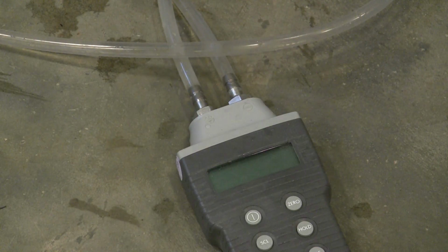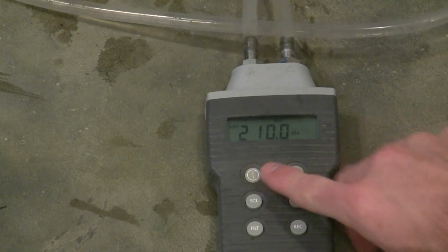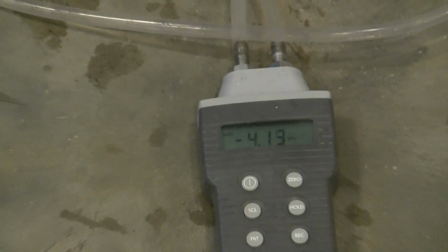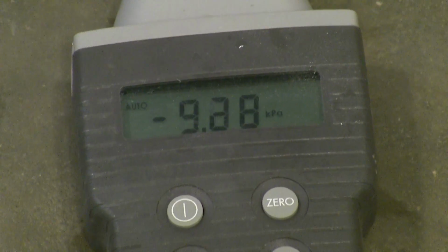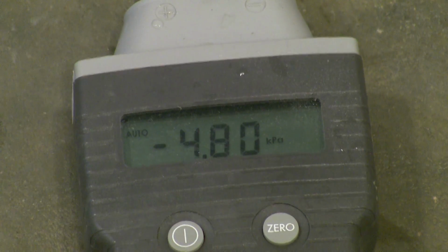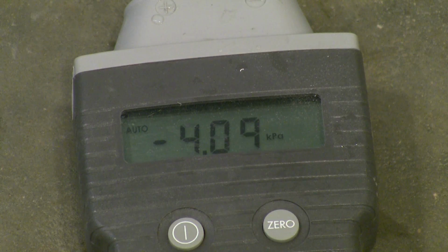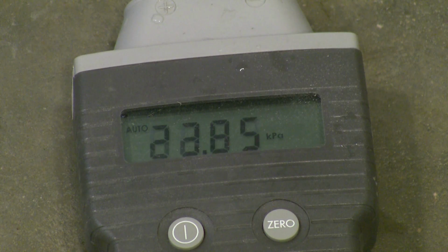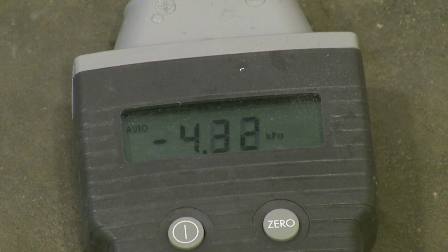All right, let's take a look at some of the data that we're getting through this device. Seems like we're losing a little bit more pressure through here than we did through the other one. I'm going to double check the 0. So closing the valve should, once it stabilizes, take it down to 0. It is. That's good. Open the valve back up. And let's take 5 measurements so that we can get an idea of the average pressure loss through the long radius 90-degree bend.